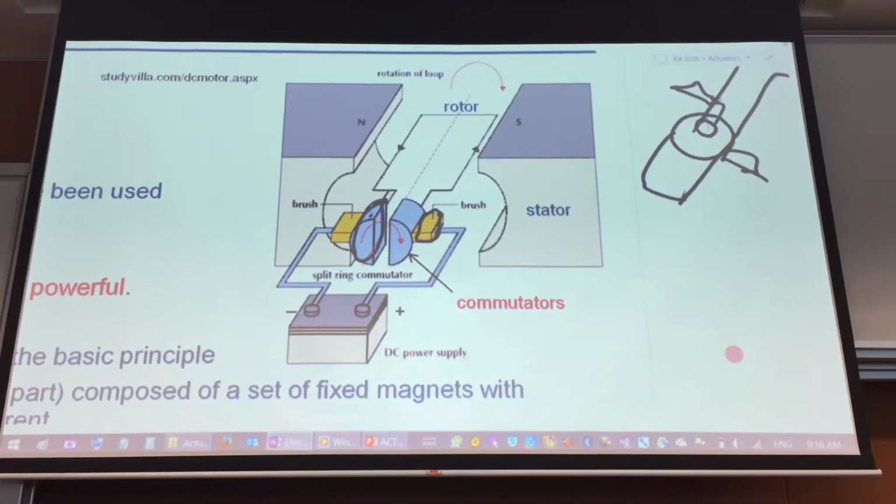When it arcs, the north and south pole are always facing that way, so it's good to arc it. In fact, the magnet is not built as a block with this cut, but as an arcing kind of magnet to provide the north and south pole. So that at any point of time when this wire frame rotates, it's always experiencing the magnetic flux cutting through it perpendicularly. So this design is still not good enough. We can improve it further.